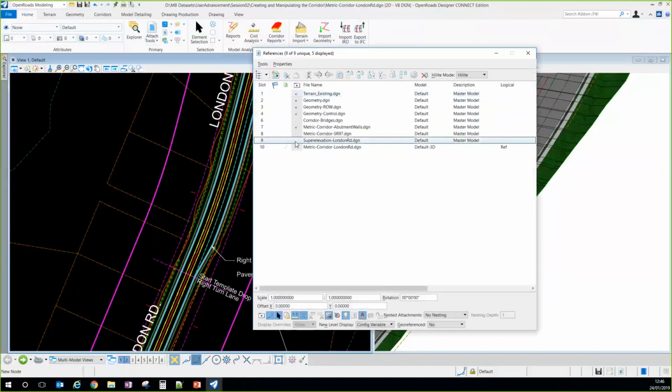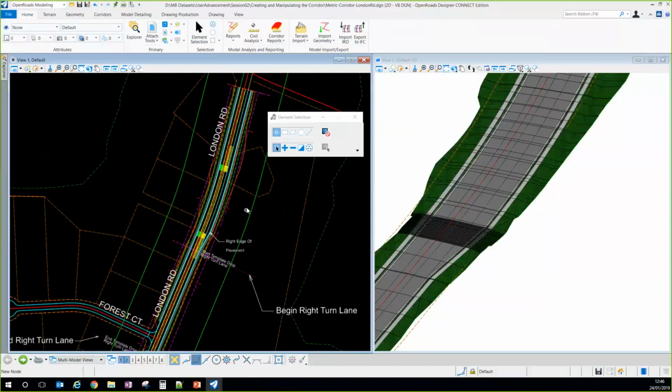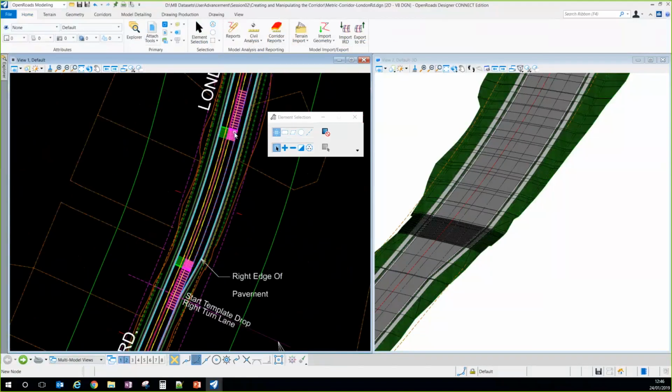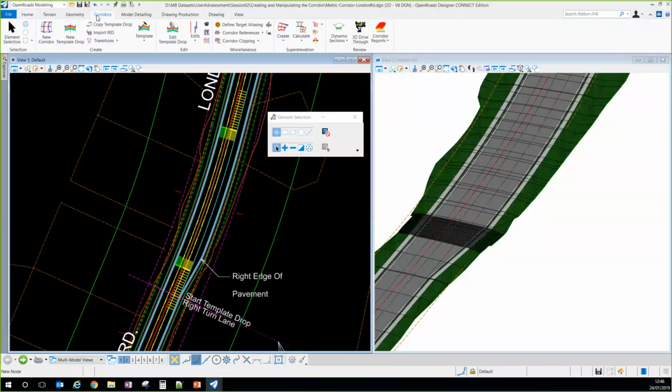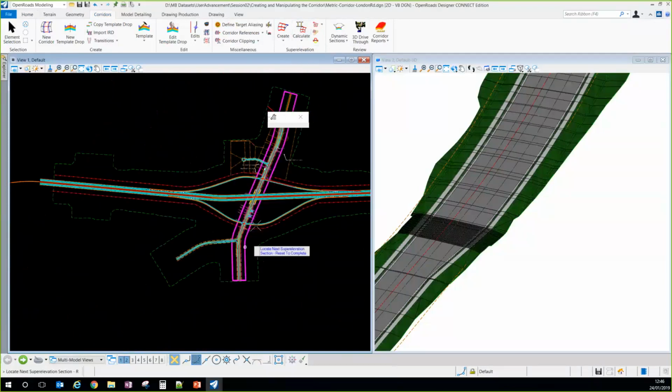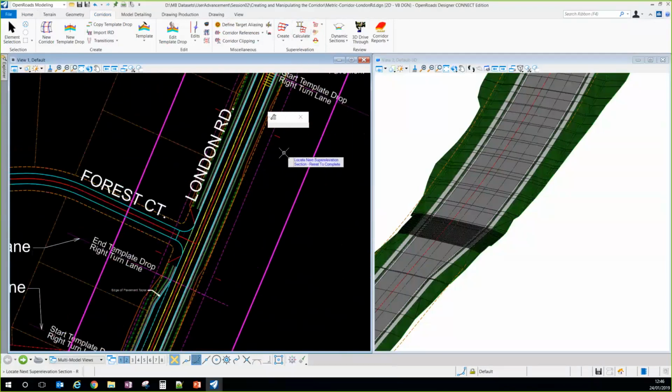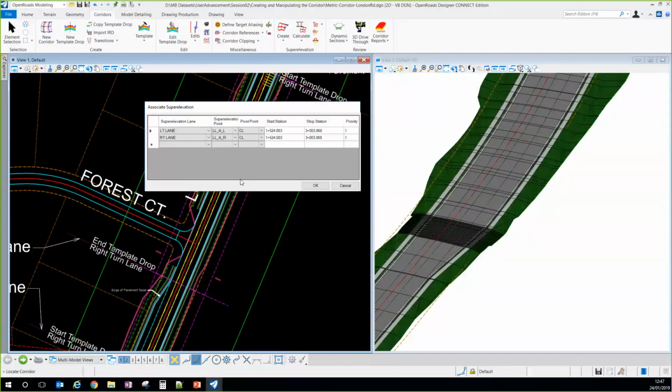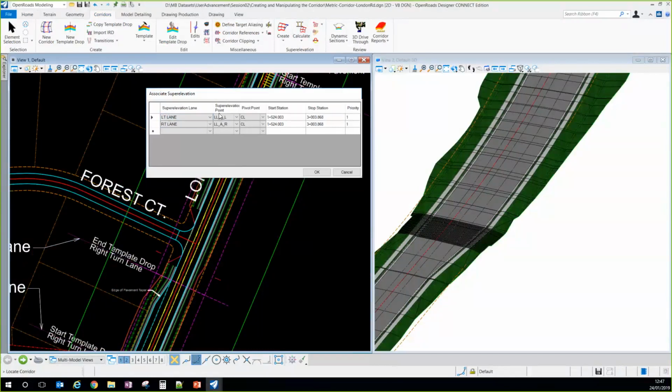I do it again. Okay, so the super elevation file contains 3 elements. This shape represents all your super elevation, and the green and the yellow are the lanes, so the right and left lines. So to apply them to your corridor, you go to corridor, assign to corridor, select your super elevation section. We have only one section for this corridor, so we just select this one, we validate, we select our corridor, so here, and we just have a look at how it works.